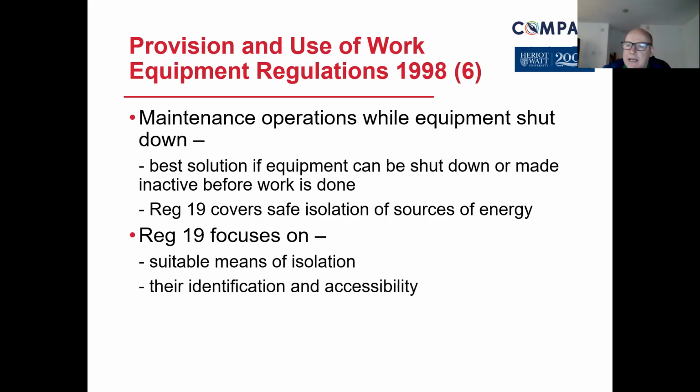On a small machine, I had a guy who broke his arm once because he bypassed the interlock. By bypassing the interlock, it meant that this table that goes from the ground position to the upright position was in the upright state and he bypassed it whilst it was in the upright state. When he opened the guard up, it stayed there for a while, and then when he was doing fault diagnosis, it dropped down. And it dropped down on his arm and broke it. It could have been worse because if there was a shear edge or a sharp edge, it could have been amputation.